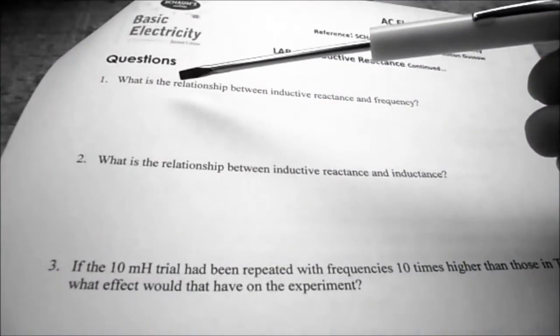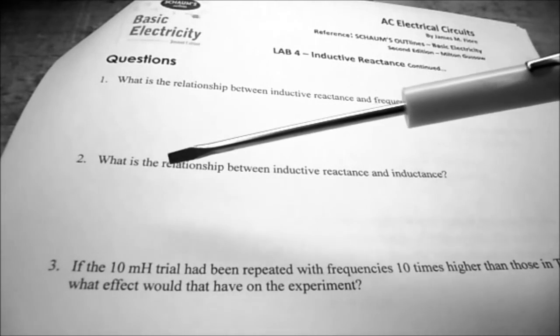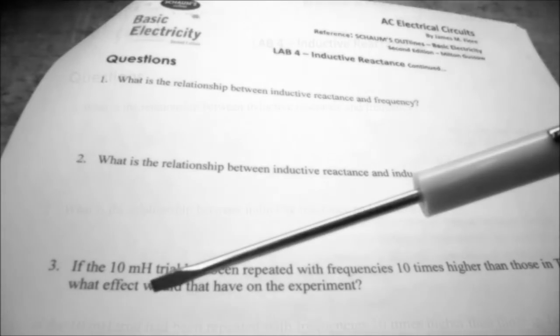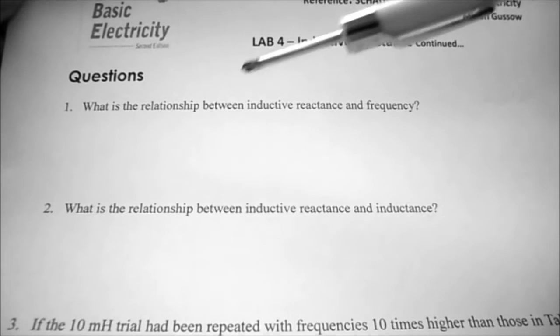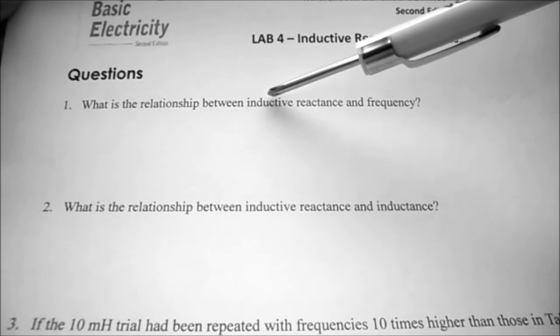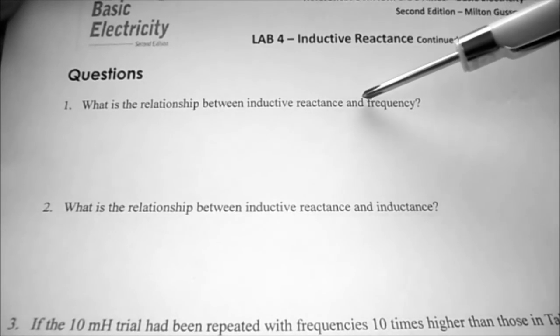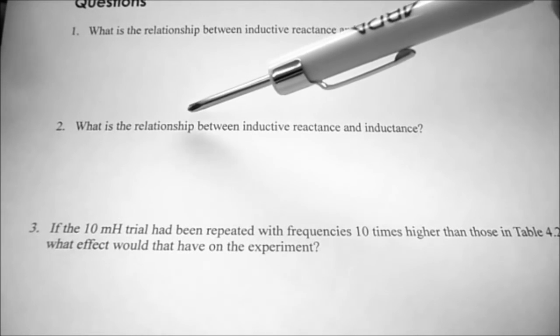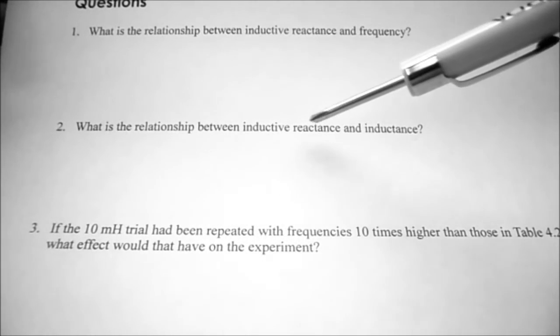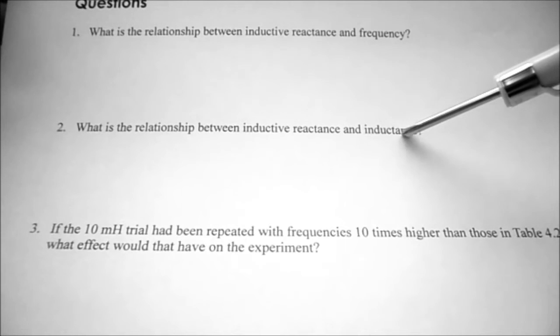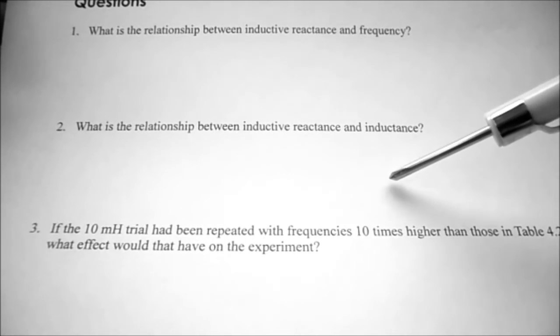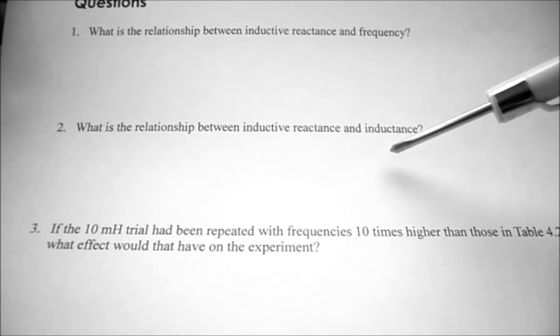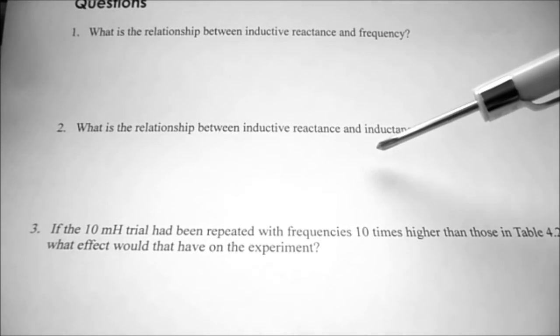As with most labs, there are questions to be answered once you've completed your graph. So looking at question 1, what is the relationship between inductive reactance and frequency? Well, I think it's linear because it was a straight line. Question 2, what is the relationship between inductive reactance and inductance? Well, we used two different inductors, and I think the slope of the line has something to do with this answer.